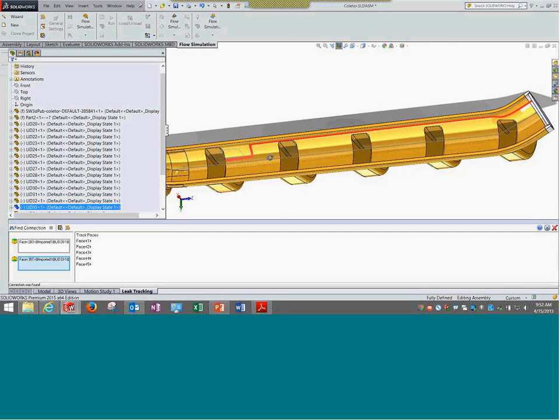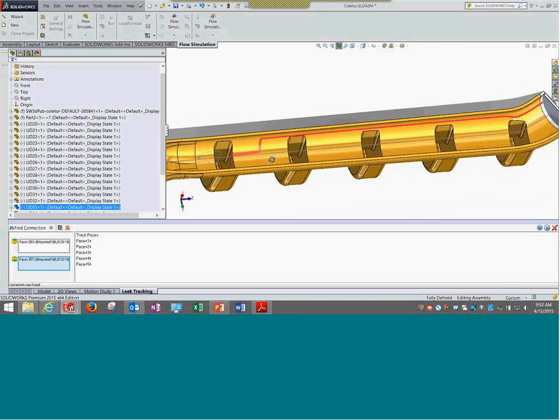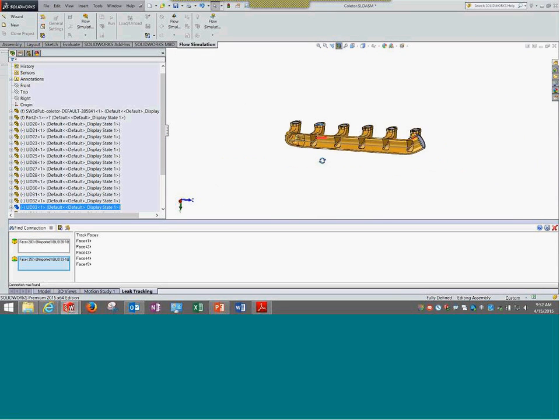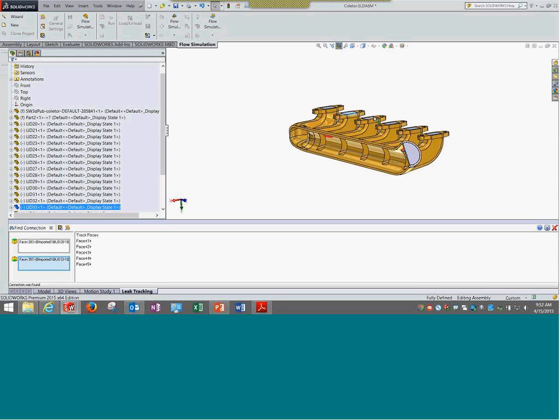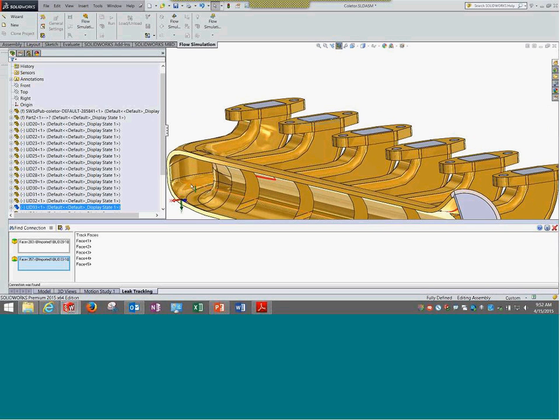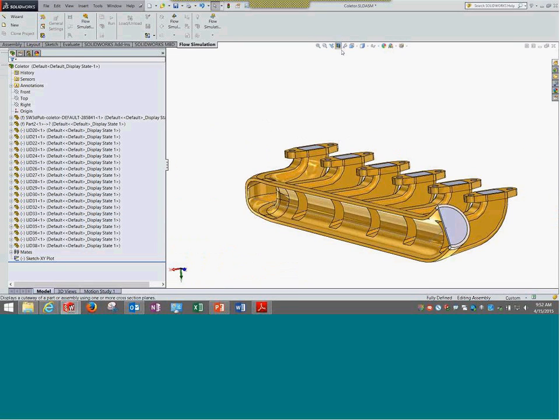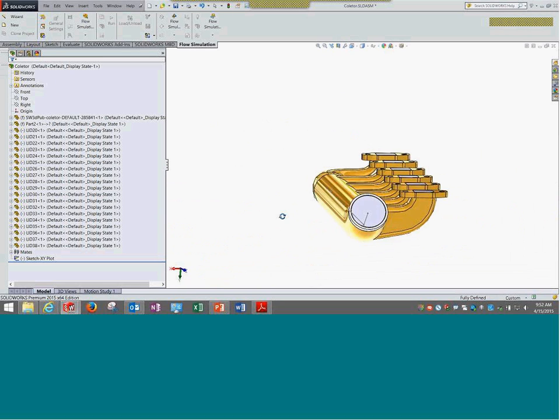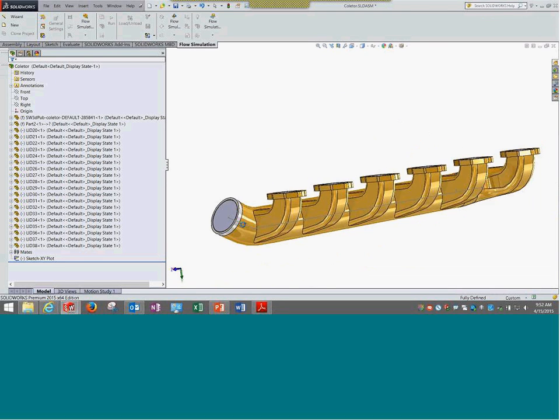It is giving you the basis through which it might be going outside. But again, if there are any holes, it will actually not go all the way till here, but it will try to escape through those holes, and that will help you understand the location where those holes are present in the geometry. So very important. Again, one more important aspect of doing flow analysis is getting or preparing the geometry for the analysis. Any questions on geometry creation?